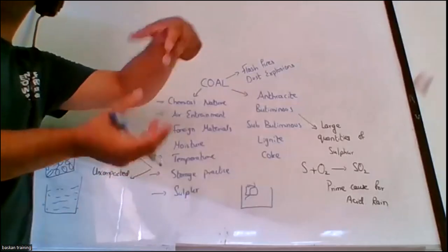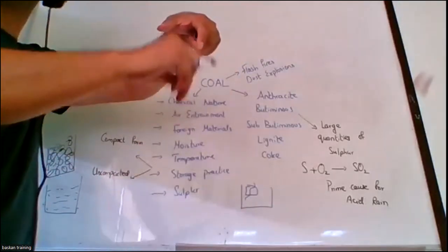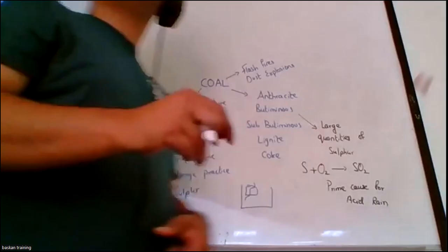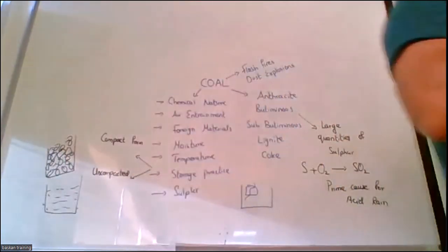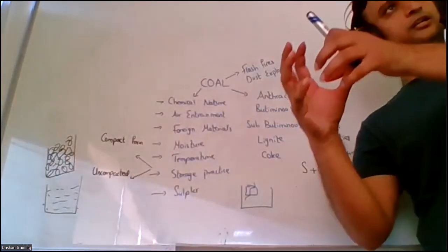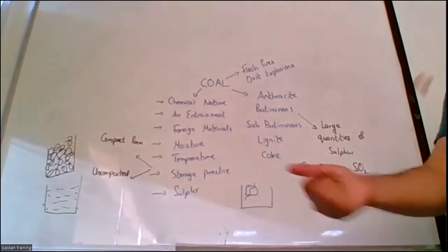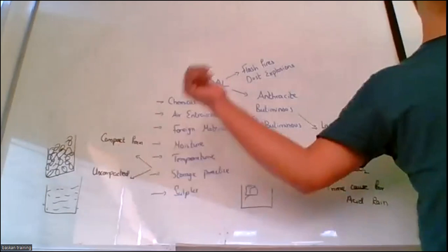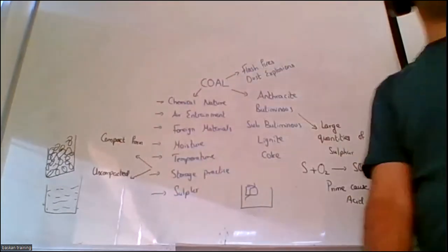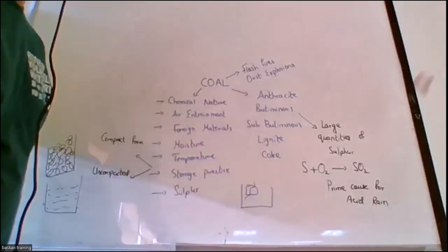So if it breaks down into two portions, again, air will pass freely. So that is the danger that we always have by storing coal. If more sulfur means more portions will break down and more air can enter and pass through. So that is why large quantities of sulfur can also affect the ignition and combustion process of the coal storage.